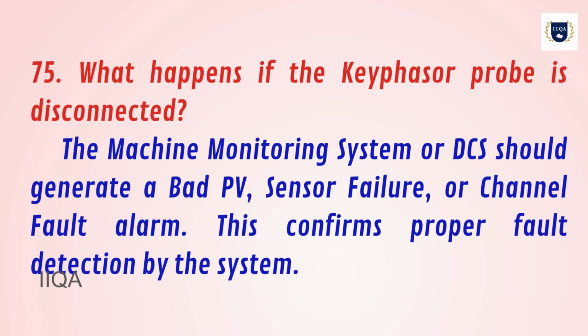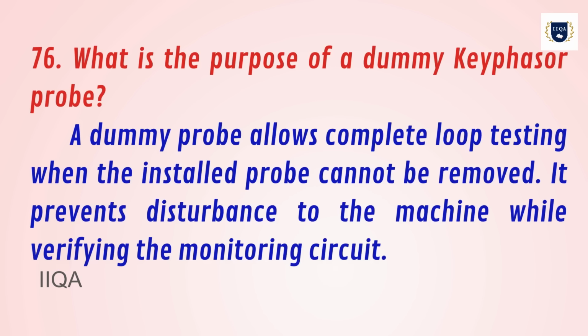This confirms proper fault detection by the system. 76. What is the purpose of a dummy Keyphasor probe? A dummy probe allows complete loop testing when the installed probe cannot be removed. It prevents disturbance to the machine while verifying the monitoring circuit.